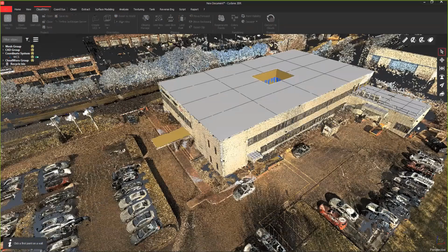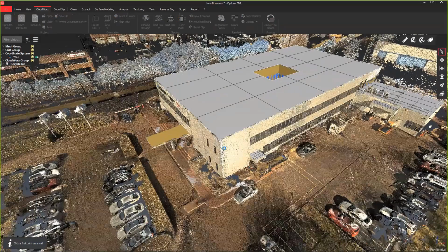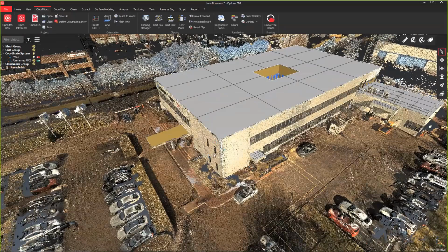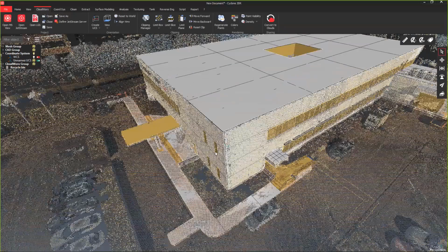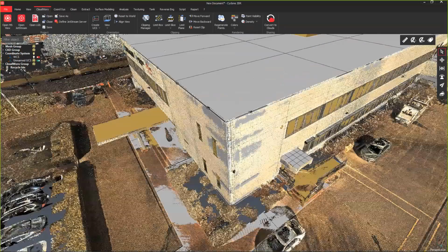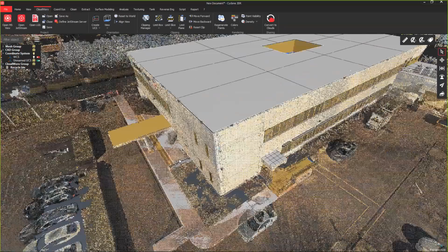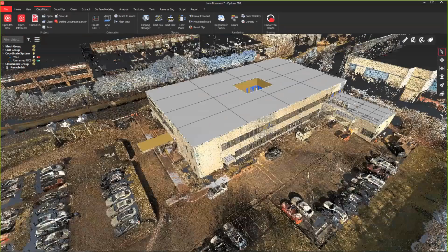And as soon as my mouse comes back here, bear with me. I'll click on that wall, and then I'll click on that wall. And I don't know how well you can see it, but right here at my mouse, there is a UCS icon showing me the X, Y, and Z. So with that, I can go back to that View tab and redo my limit box.